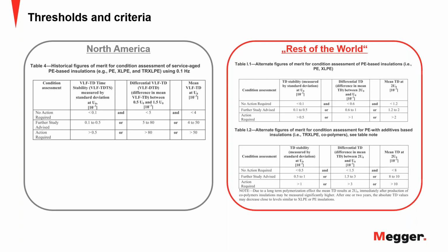So with mixed cables the method becomes ineffective. And also these additives tend to have still chemical settling processes going on. So part of these additives gas out over time, which causes the tan delta to change. So if you do a tan delta during commissioning testing, you might be misled to wrong decision making because you measure something that looks bad but actually is not.